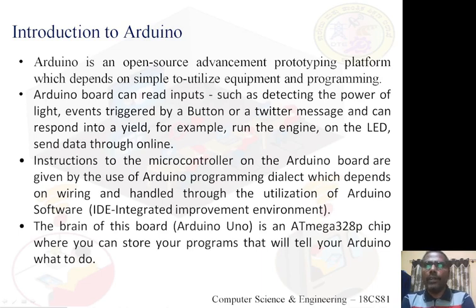That is the Arduino software, which you call the Arduino IDE, which is open source. Using this Arduino IDE, you can program the microcontroller to perform a set of instructions. After writing the program source code in the Arduino IDE, compile it. On successful compilation, you can upload it to the Arduino board, I mean to the microcontroller on the Arduino board.